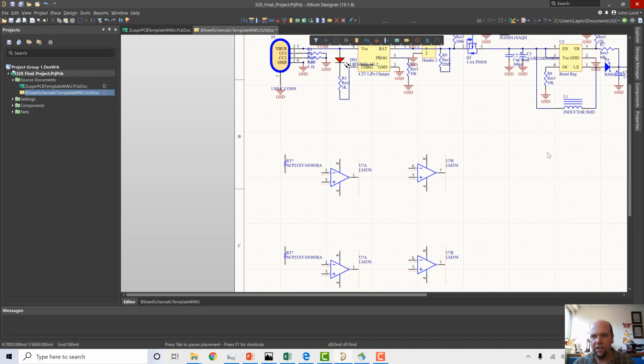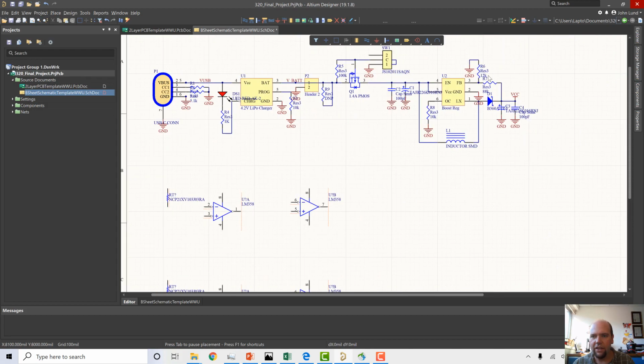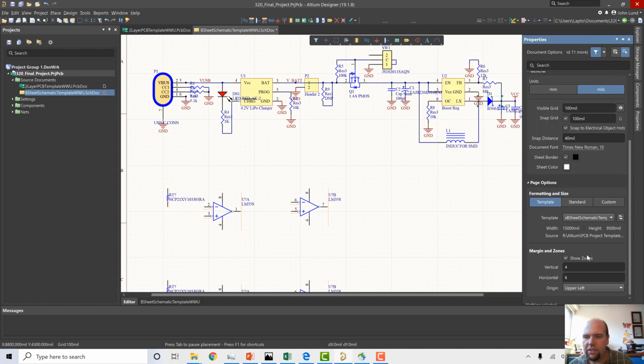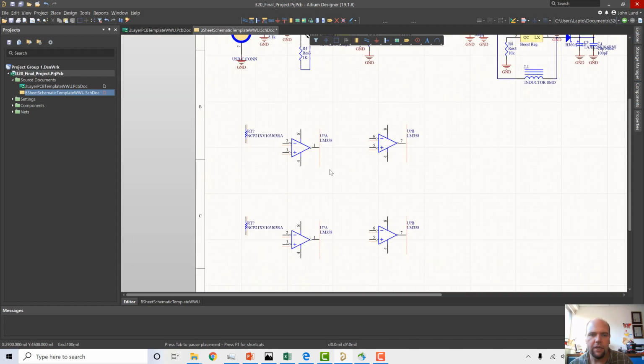So if you've already done that, we might have some other parts we want to sort of look at then. I might have done some of these wrong, so I might have thought I was selecting a certain footprint when I wasn't. One thing to note though, if you change the footprint, next time you reconnect, it's going to kind of throw things off a little bit. But anyway, you can always go back and change the footprint. If you have multiple footprints associated with a part, you can change it by actually looking at the part properties itself.